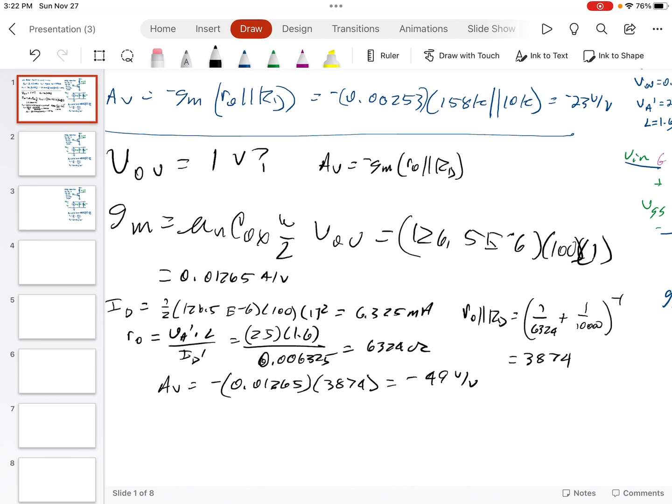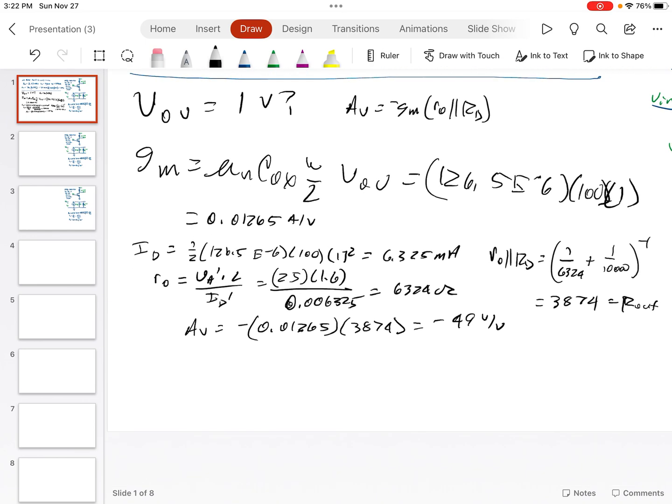but we really hammered the output resistance, because this is actually equal to R out, and that could be a problem, depending which way, what it is we're trying to do, but that certainly could be an issue. But we did get more current, more gain.